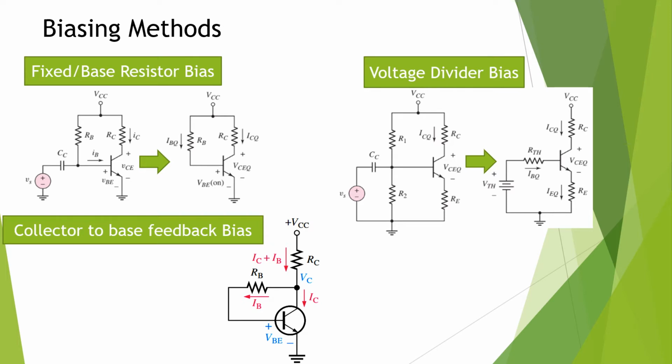If you want to go for the large signal analysis, we have to remove the signal source. I already told you the superposition principle, right? The superposition principle states that if the circuit contains multiple sources, the response of the circuit with the multiple sources is equivalent to the sum of the responses of the circuit with the individual sources.